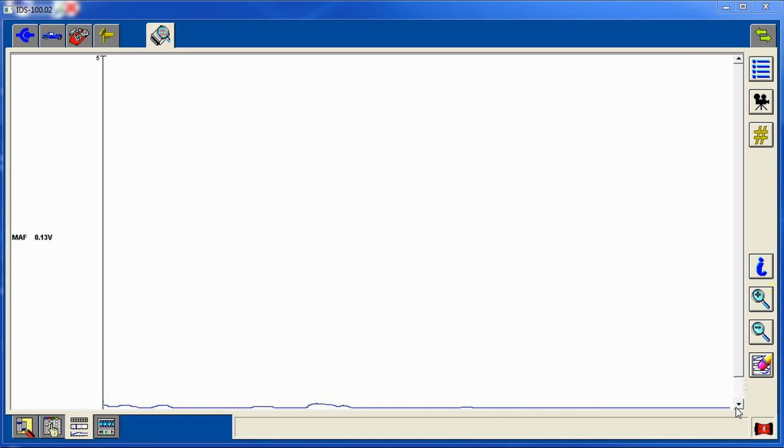Okay guys, you can see here the mass airflow sensor, key on, engine off, is reading, well, I'm talking and moving air, so it's going up right now, but it's reading 0.14, 0.15, so that's like 150 millivolts, okay? Dead idle, no air going through it. This should say 0.01, 0.02, something very, very minuscule where it's not going to affect the reading. What I found before I even took the mass airflow sensor off is it was sitting here just like this, 0.13. It's like 130 millivolts, 140, 150. Okay, so that's the old one.